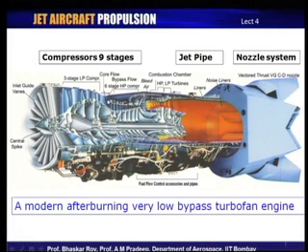And then this low bypass engine creates a bypass which goes through this entire process, and then one can use this bypass, which is actually cold air, relatively much colder air, to feed into the liners which we talked about earlier, which is used around the entire jet pipe. And now, you can see the bypass air has a very good utility value, that it goes into the liners for creating a very cold safety zone for the jet pipe.